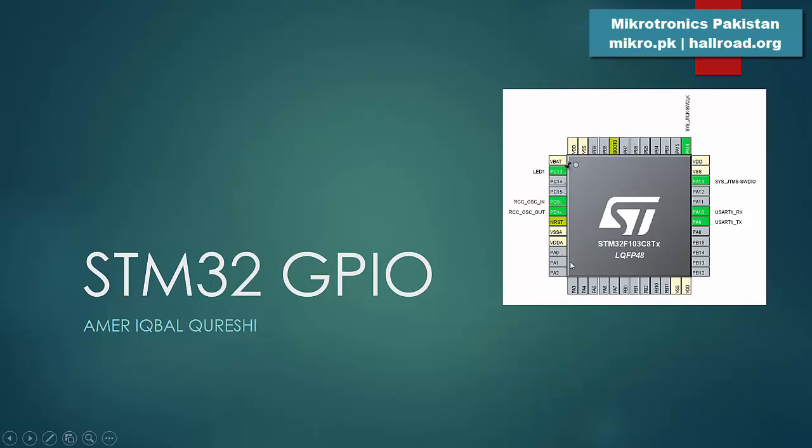This is the actual microcontroller. This is an integrated circuit which has 48 pins. So the number is STM32F103C8. As you can see, some pins are for power supply, like this VSS and VDD are power supply pins.